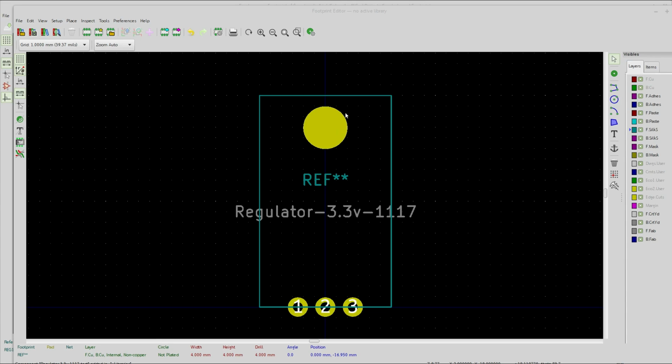But I did want to talk about one more point of interest having to do with holes, the pad size going around it, and this thing called the annular ring. So right here, again, this is a through hole. There is no extra pad on the outside. When I keep saying this extra pad on the outside, like right here, the yellow area is that extra pad, well, that is the annular ring. If they're going to drill a hole through this, you want to make sure that the pad diameter, the annular ring, is large enough that if they screw the hole up a little bit, it's not going to be on the outside of your pad.